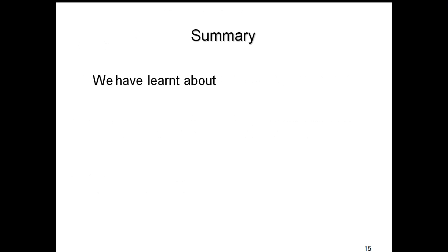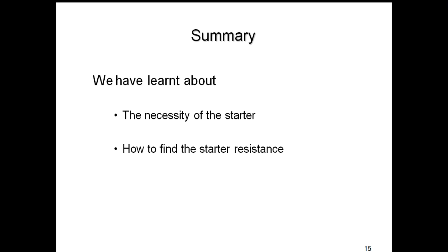And from this presentation, we have learned about the necessity of starter, that is to limit the starting current, and also we have found the starter resistance.